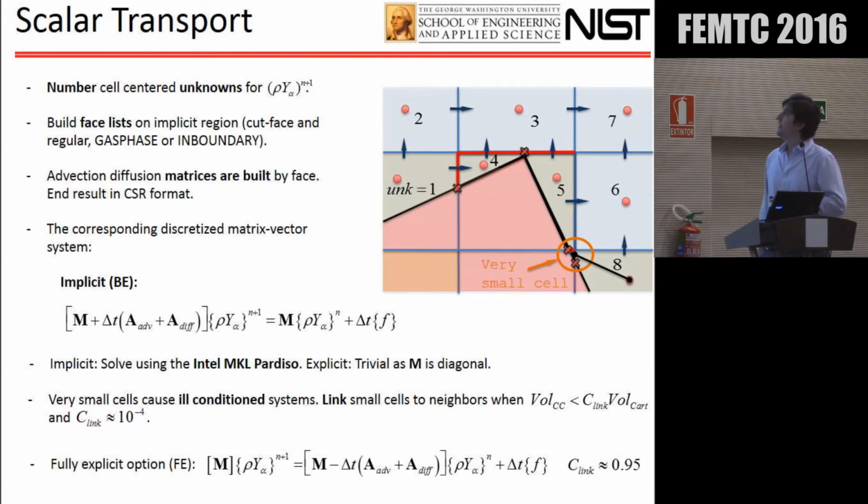So, for example, here we have an equation which is an implicit solution. We have a matrix, an advection matrix, a diffusion matrix, and this is the evolution equation. This has to be inverted. This advection matrix will change, and in general for LES, which is probably what everyone uses here, the diffusion matrix will also change. So this has to be solved every time step, actually every sub-step.